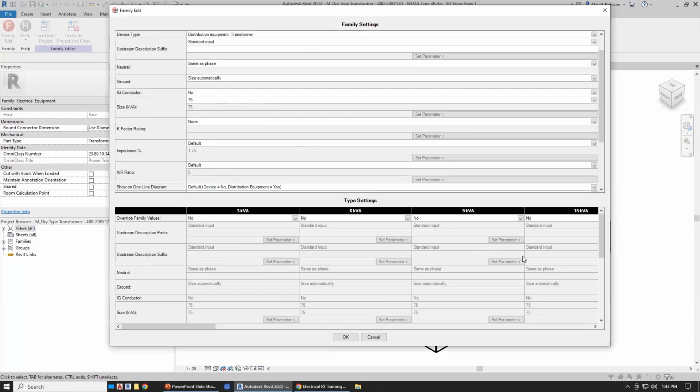So this is how you could take your existing families that you have and get this information loaded into them from Design Master so that when you're using it on future projects, you've got these values specified ahead of time and you're not having to do that as a second step. We have to have this in Design Master through our interface because Revit doesn't have a place to put any of this information. So we had to create a framework for storing all this information. So you have to use our command to get this information into your families, because Revit otherwise doesn't know about any of this stuff. But if you put it into your family, then you can use it in your projects.